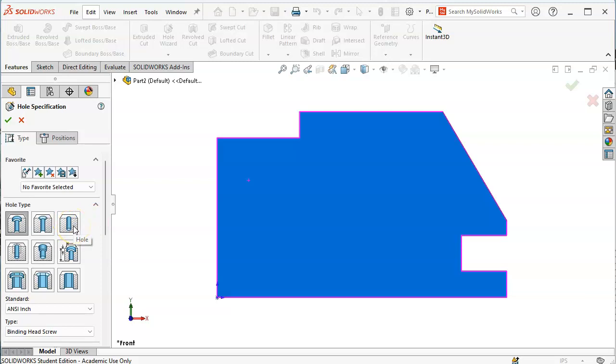For this assignment, we're going to be doing the through holes, since all of these are given as diameters, but then as an example, we'll go back and we'll probably change the 1/4 inch to 1/4-20s. All right, so that's just a matter of there is our straight tap, a tapered or a pipe tap. A pipe tap gets tighter, seals more for fluid retention.